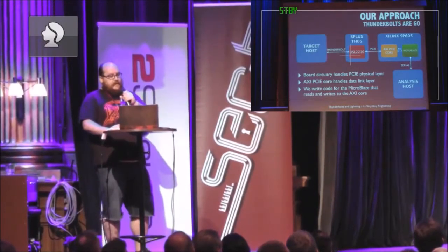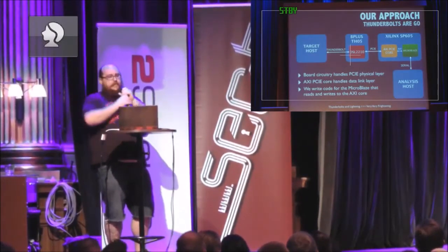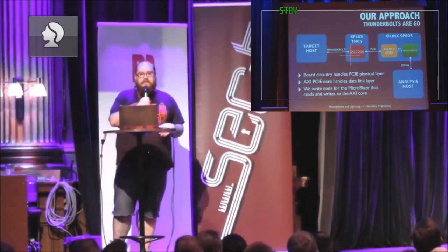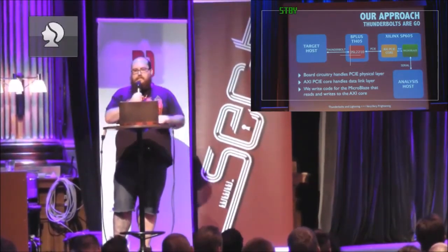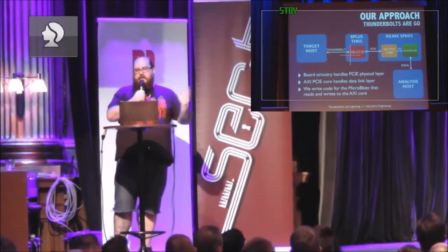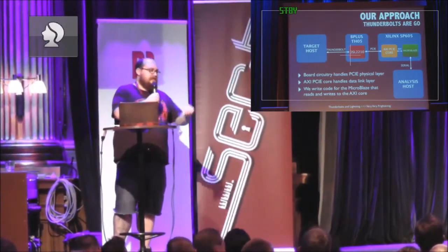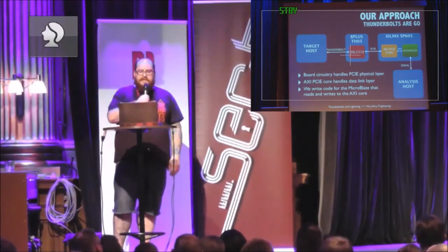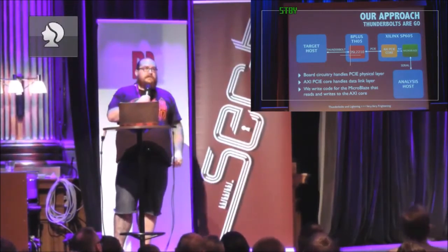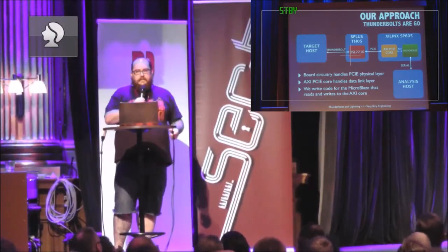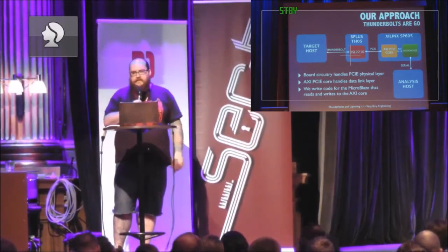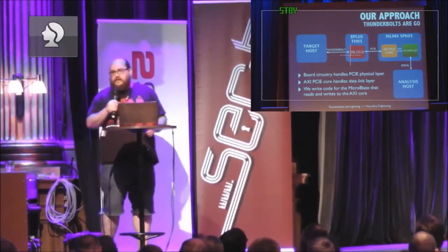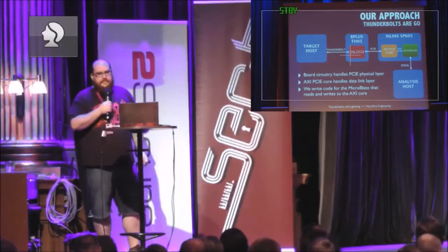So we've now got our, I don't think I even mentioned before, the Xilinx SB605 is the development board that we use. I'll show you a photo of it in a sec, point out all the bits. It's got our FPGA on it, and it's got a PCI Express finger hanging out of the side of the FPGA. It's because most of the boards that are built by FPGA manufacturers with PCI Express are basically designed for building new networking hardware. So they have every feature under the sun, and most of them are really expensive.